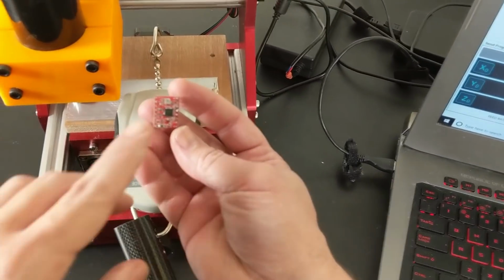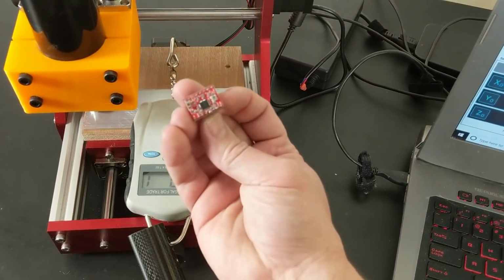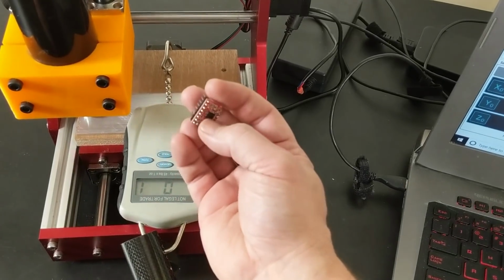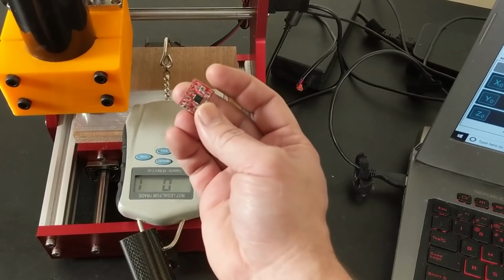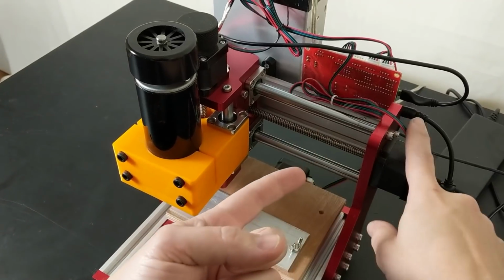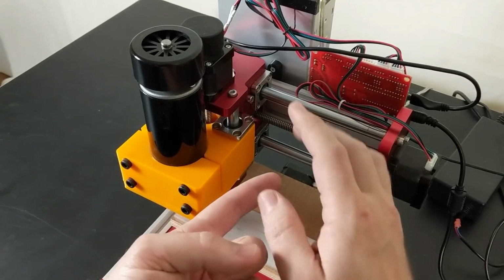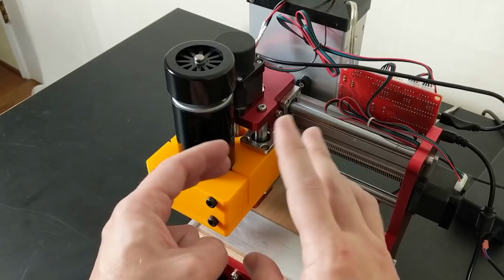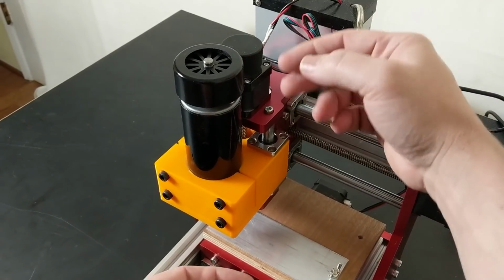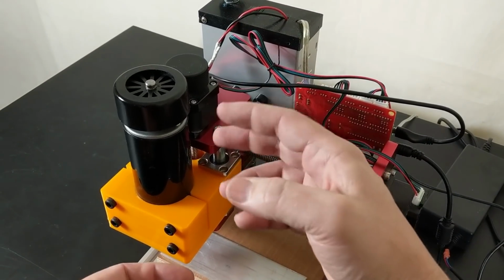So I was able to get a similar pull factor from the stock control boards at a VREF of about 0.8. So you might want to go with that if you are not going to replace these stepper sticks. Okay, so the machine is adjusted so that it's got a good amount of push through the material. The new spindle is mounted and working fine, and we're able to use the tone generator to figure out how